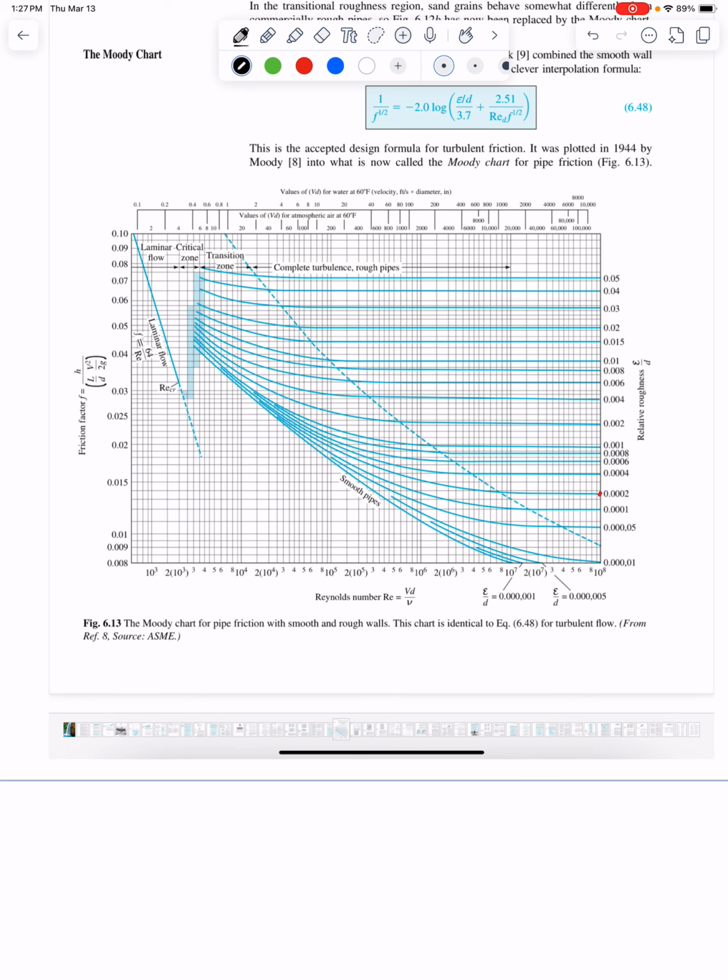Okay. So early in the problem, we solved that epsilon over D, the pipe characteristics roughness ratio, was 0.0013. So that pi term, in terms of the Moody flow chart, is kind of like a family of functions. Based on that value, you have a different function to represent that pipe's characteristics. Our pipe characteristics is between the families of 0.001 and 0.002. Therefore, our function, I expect, looks something like this, somewhere between those two lines. It looks a little skewed and bad, but that's what it should look like.